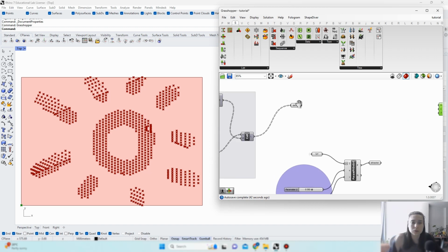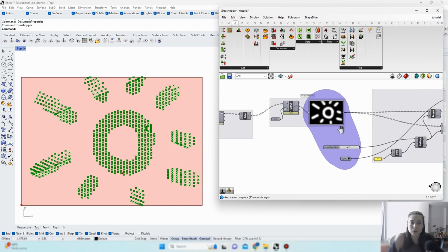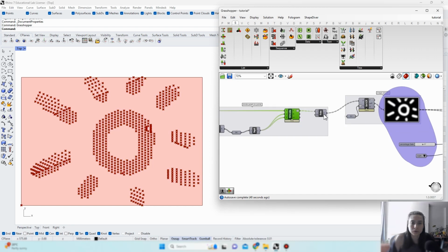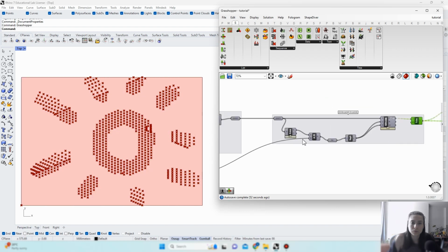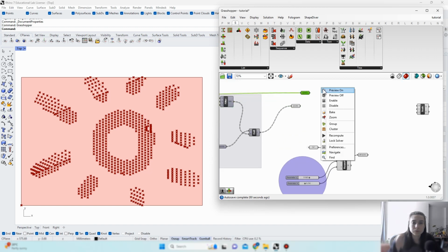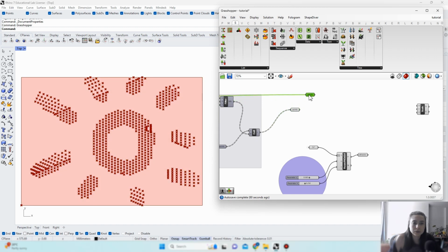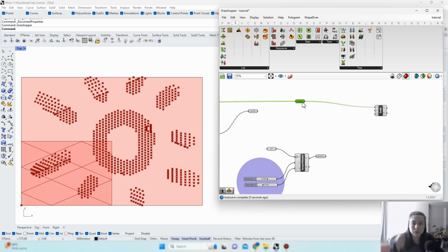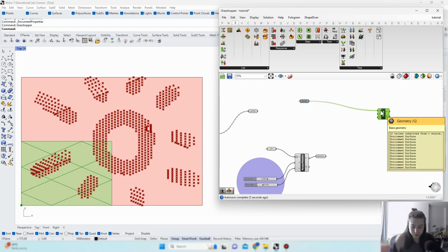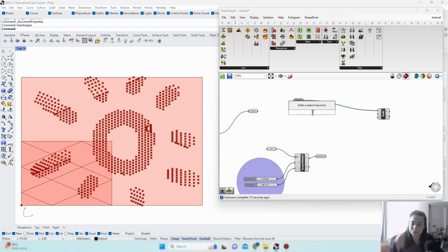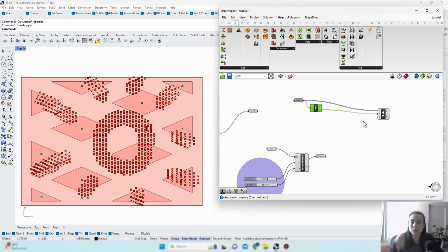Okay, but instead of points, we will scale panels because it's a little bit better and I think it's also faster. And we also learn transformations, which is the goal, or one of the goals at least. We bring the panels here, which are those guys, and that will be our geometry to operate with. Each panel has a center point, which you can make through this component. It calculates the central point.